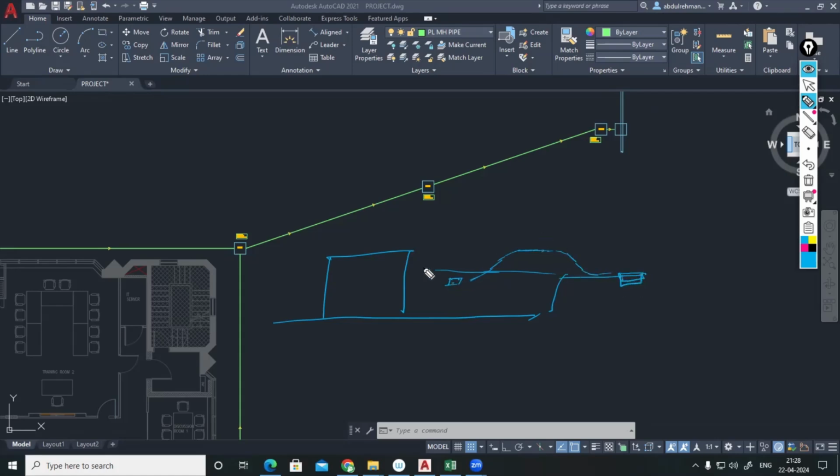Anyhow, from manhole number 5 to manhole number 7, it is not possible to connect like this because the land is like that only. So in this scenario, what you have to do? Anyhow, this pump you have to make as a holding tank. It means you have to make this a bigger tank, at least 30-minute storage, if you're not facing any power issues. By gravity, we have a cover here and a manhole there. By gravity, it is not possible to transfer the water, right? That's why we have to transfer it with the help of a pump.